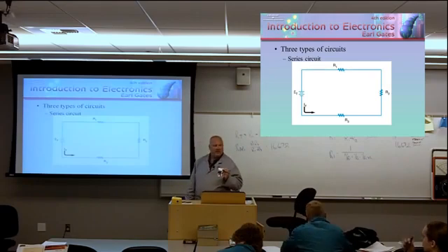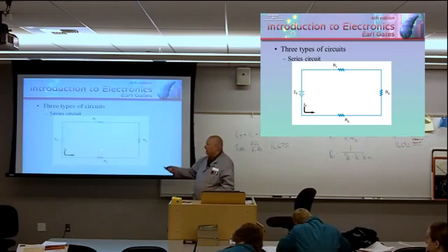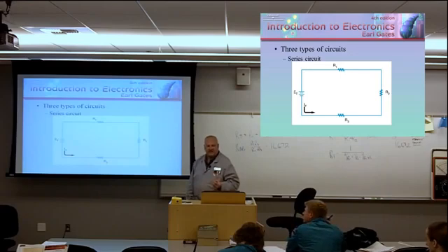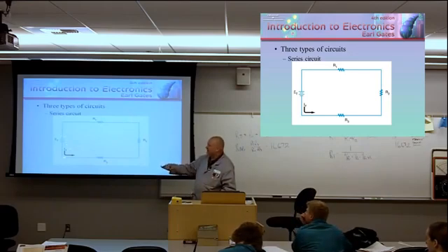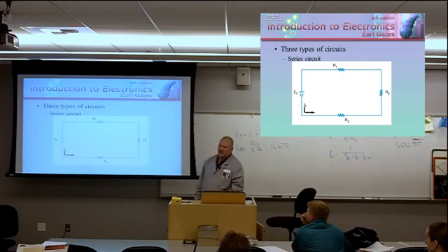Meaning, I've got a resistor here, a resistor here, a resistor here. These 3 resistors cumulatively add up to the total amount of resistance in the circuit. This electrical pressure here encounters this total resistance and allows this amount of current to flow. This current has to travel the entire path of the circuit. That is the most important thing about a series circuit, period.